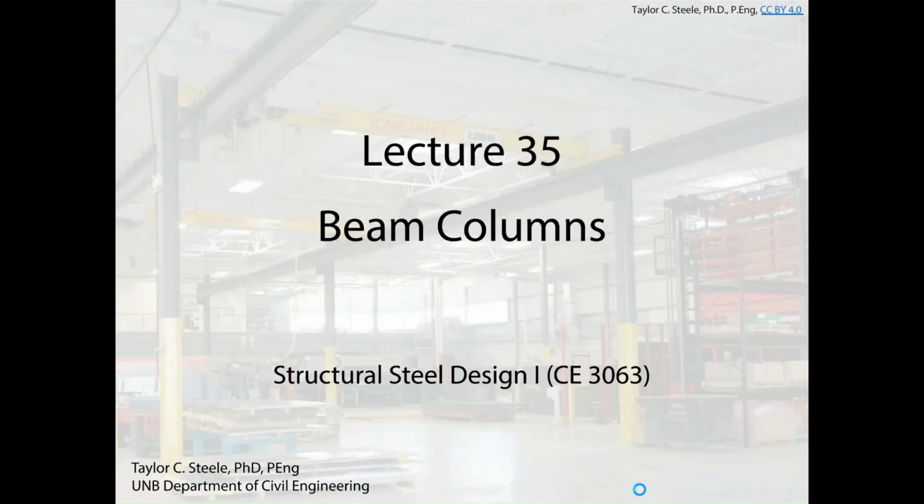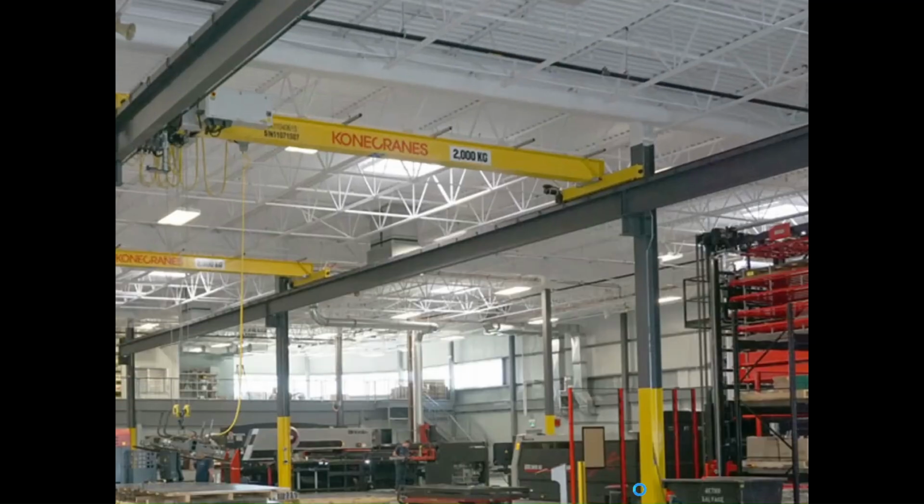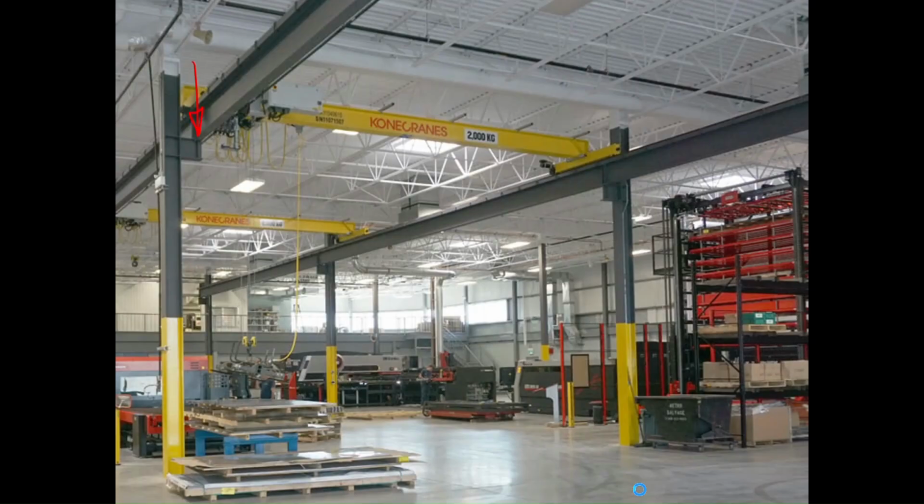Whenever we have combined compression and bending, these members tend to be called beam columns. Beams take bending, columns take compression, and so if we have something that takes both bending and compression, we call it a beam column. They're pretty common. In the example I showed the other day, a crane supporting column with a standoff, there are going to be point loads acting on the standoff, and that eccentricity is going to cause some bending, and the vertical force is also going to cause compression. So there's going to be a bending moment diagram for that member and a compression in that member as well.